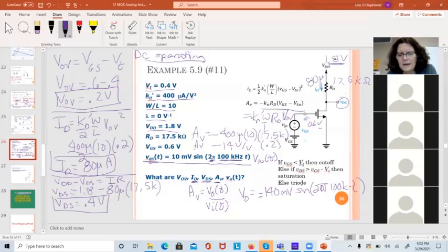Having that negative sign in there just kind of bothers me. So we could write this as 0.14 sine 2 pi 100 kt plus or minus 180 degrees. It doesn't matter, it's the same thing, and that would be in volts. So that negative sign can also be represented as a phase shift.